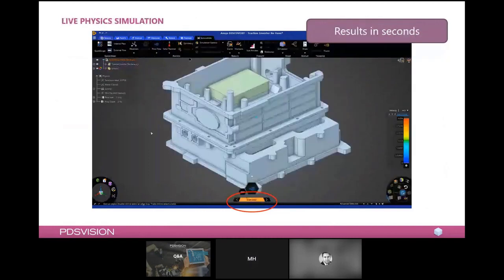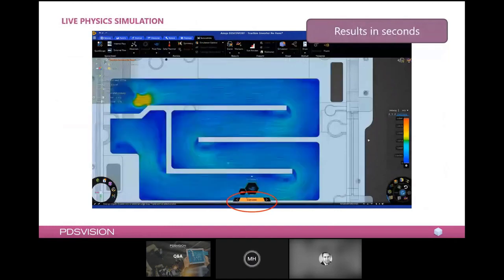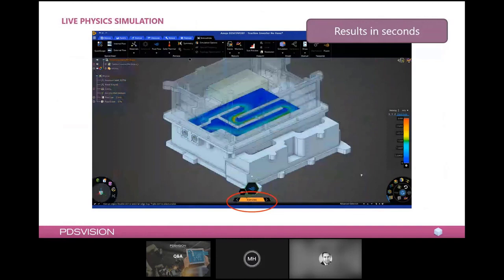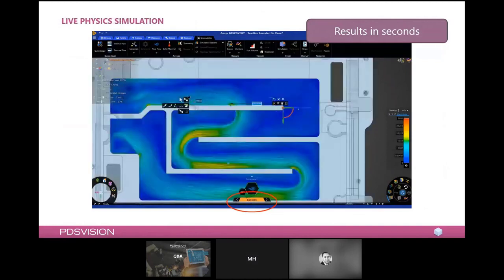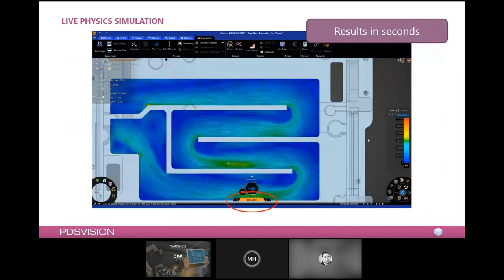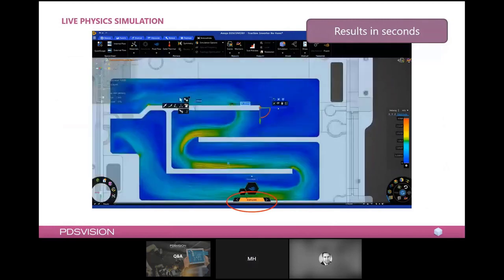Then the actual simulation part of it, the Ansys Explore mode. If you make some changes in there, let's say to input parameters like velocity, or a change of geometry, the results will update instantly. And that's very nice for finding out what the effects are if I tweak this a bit, what will happen if I do something small in here. So you can concept out what we get if we change something. Would this go better or worse than the original design?